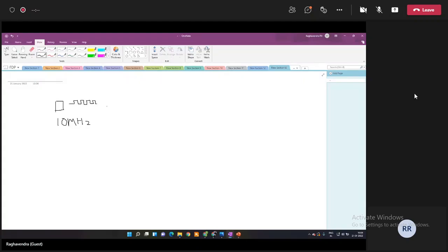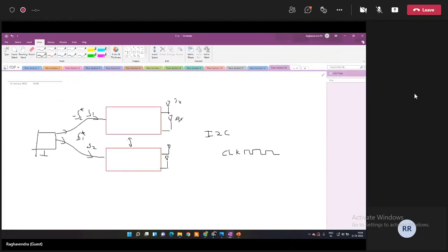Now, like I said, when we came to those IQ impairments where I said you have different DC offset, the mixers have different gain. Similarly, in different USRPs, you have different crystals, and each crystal does not produce exactly precisely 10 megahertz. There may be a crystal that produces 10.0001 megahertz. There may be a crystal that actually produces exactly 10 megahertz, so on and so forth. So what happens is, when I try to transmit a signal from two different USRPs, and I try to do a MIMO signal from two different USRPs, the carrier frequency generated here and here are different.